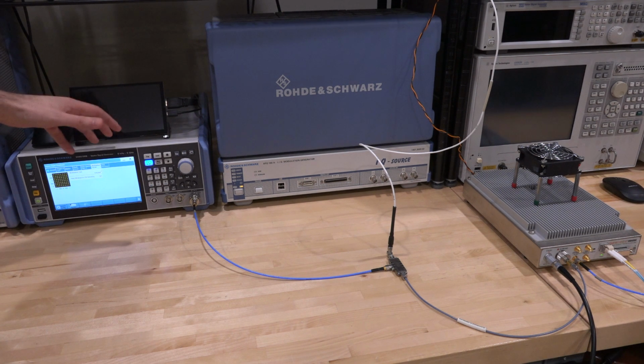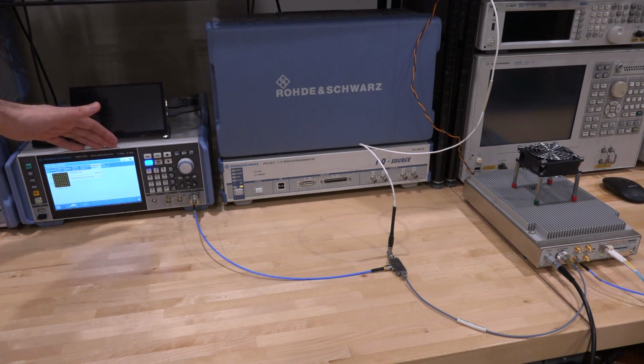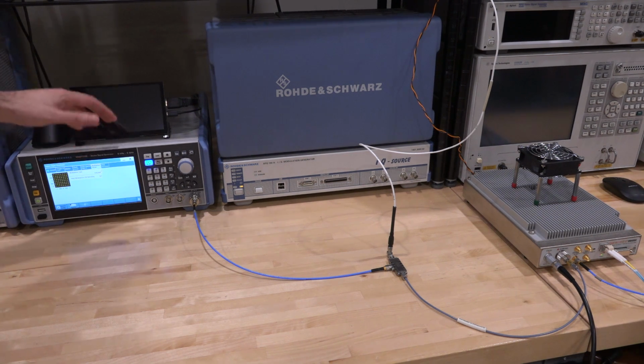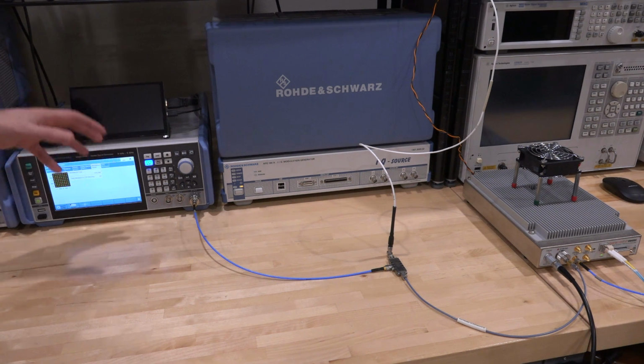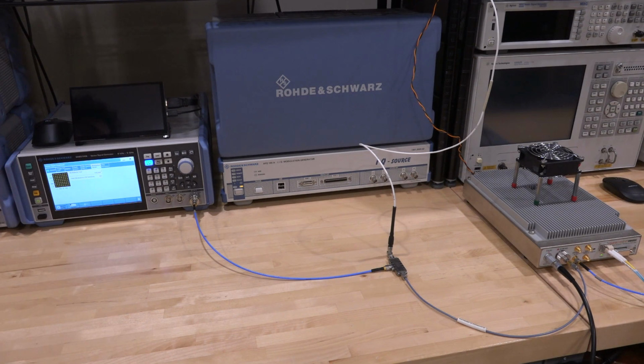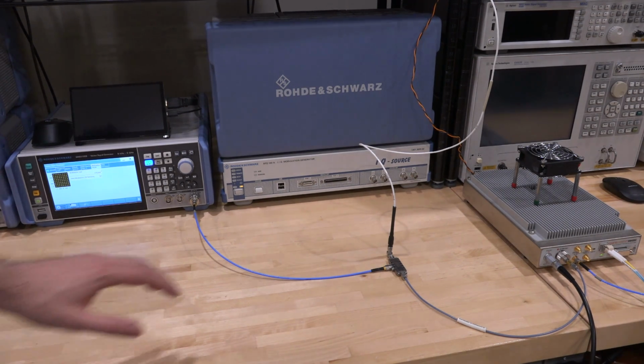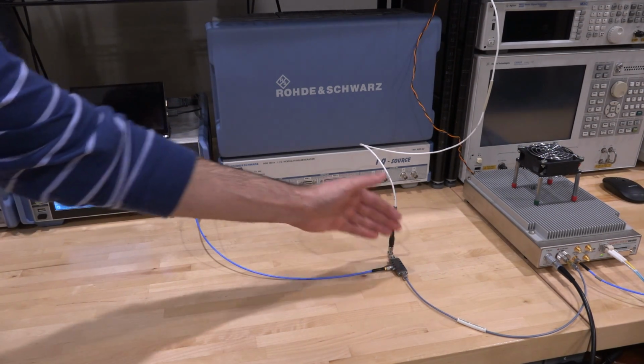Now for our IF input into our mixer, we're going to use the Rohde & Schwarz SMBV100B, which is an exceptionally clean vector modulator synthesizer box, and we're going to generate a 64 QAM modulation on a 3 gigahertz carrier. This thing can produce really low EVMs. I use it in the lab all the time. And that's going to be the IF input going into this millimeter wave mixer.